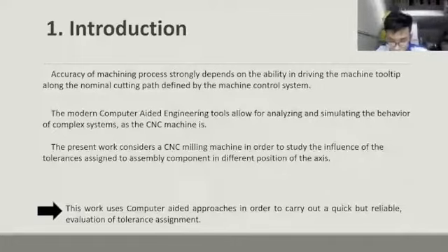Errors due to the machining process have direct effect on the geometric accuracy of the machined surface. They include mainly cutting force variation, which causes tool deflection, and thermal effects, which deform the tool. All the sources of errors are addressed in the scientific literature.